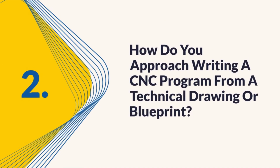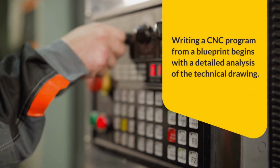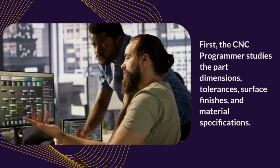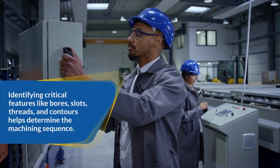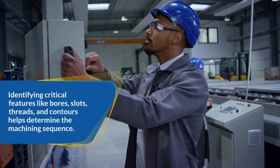2. How do you approach writing a CNC program from a technical drawing or blueprint? Writing a CNC program from a blueprint begins with a detailed analysis of the technical drawing. First, the CNC programmer studies the part dimensions, tolerances, surface finishes, and material specifications. Identifying critical features like bores, slots, threads, and contours helps determine the machining sequence.